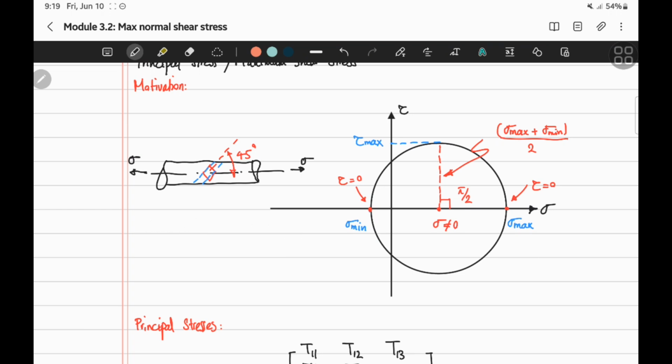And also, if you have, for example, T1 equal to T2, which is not equal to T3, so you have two principal stresses equal to each other, then this corresponds to E1 and E2, let's say, or N1 and N2, then you will have an infinite number of solutions that you can get by rotating E1 and E2.